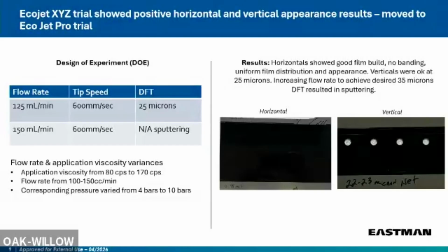Now look at the same results. This is a vertical panel, 90-degree angle. Very good for sag. So this was on the lab applicator, XYZ applicator. And like I told you, this was after a series of experiments in optimizing the SCA dose, the RCA dose, the application parameters, we got this result. So we are very happy that, okay, we almost solved the problem.